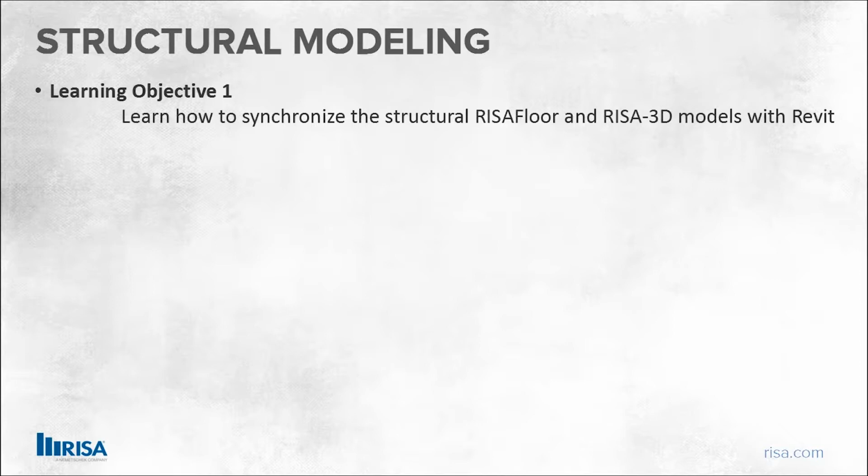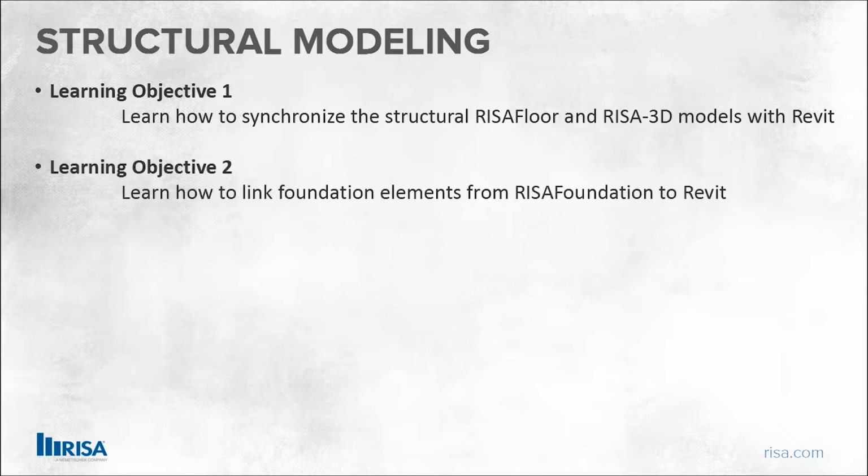We have a building, we're talking about something that is going to be a building structure, multiple stories. We know that there's a diaphragm, we're carrying loads down the structure. That's a RISAFloor classic kind of model, and it does the gravity design. We'll take that over to RISA 3D. In RISA 3D, we'll do the lateral design. So we're going to first start with that.